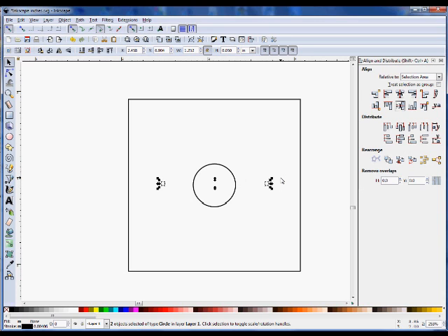To get actual measurements on them, you would come down here and drag this line down. So it is like this, and let's say you wanted to have this a 1/2 inch away from here. So what you would need to do is highlight this box, and its measurements are here, X and Y coordinates.